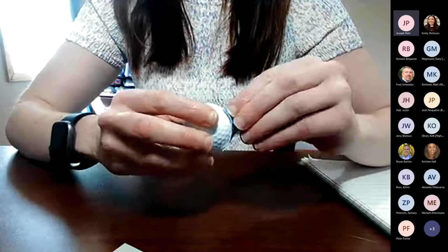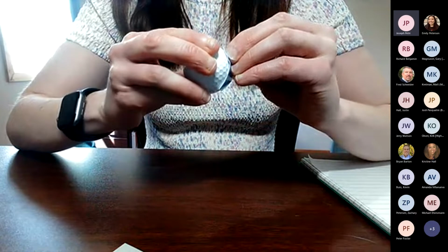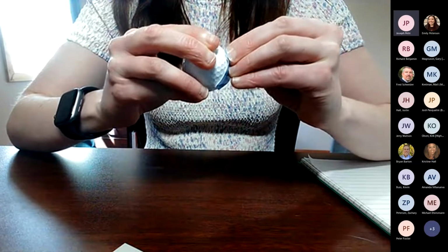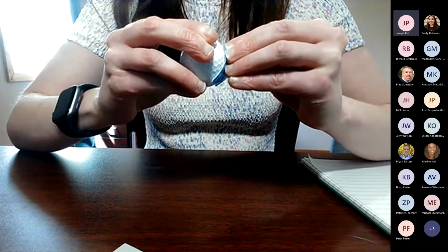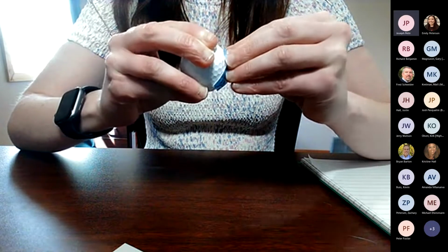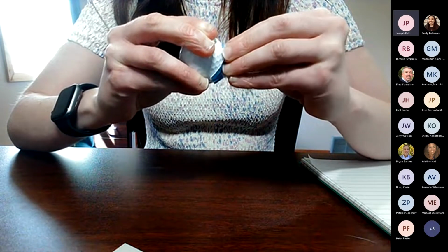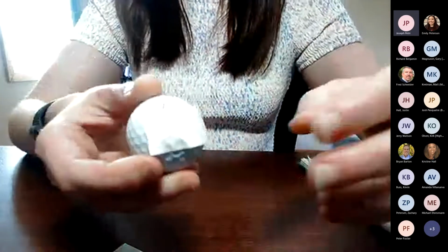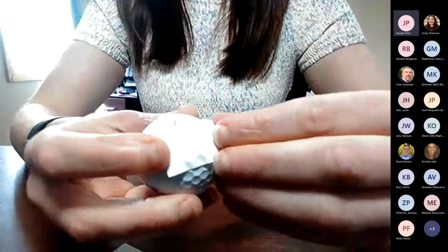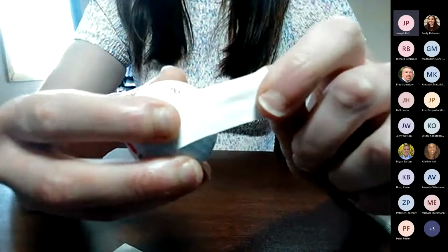There is another version that Paige is going to show you in a second, called 8926. In a thermally conductive tape that provides adhesion, not just gap filling, but high adhesion, it has a 1.5 watt per meter Kelvin thermal conductivity, tested to ASTM D5470. This tape right here has this blue liner on one side, and you can see Paige removing it. This is an example of our 8810 thermal tape. Go ahead, Paige. Yep, so that means 10 mil thickness.